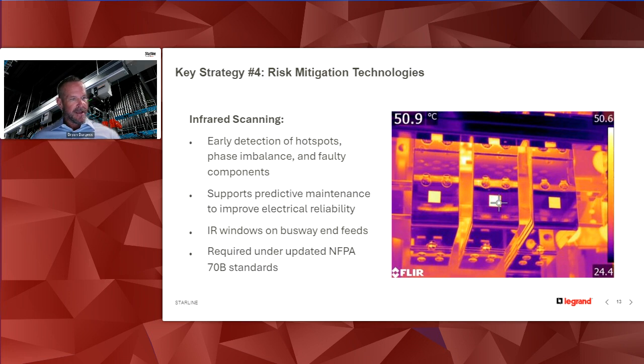And now this is required under NFPA 70B. So NFPA 70B, on January 1st, 2023, was updated from a recommended practice to now a required annual scan, for anything over 400 volts. So it's something that has to be done now, where before it was just a recommendation. So something to keep in mind there, and that'll turn into a compliance issue, I'm sure.